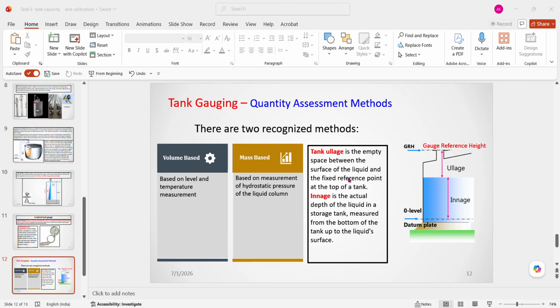IS means intrinsically safe. This IS designation means the circuit is designed with low voltage. The circuit connected here has very low voltage and current, preventing any spark. There will not be any spark or thermal ignition, even in an explosive or highly inflammable tank environment.